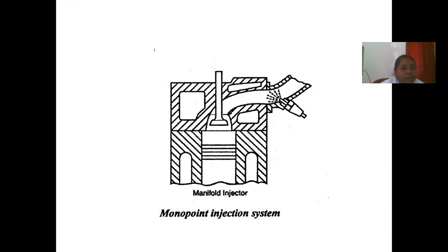In the electronically controlled gasoline injection system for SI engines, fuel supply and timing are controlled by electronic means. Electronic fuel injection has developed with the development of solid-state electronic devices such as diodes and transistors. These days, these systems are commonly used as they function quickly and respond automatically to changes in manifold air pressure, engine speed, crankshaft angle, and many other secondary factors.